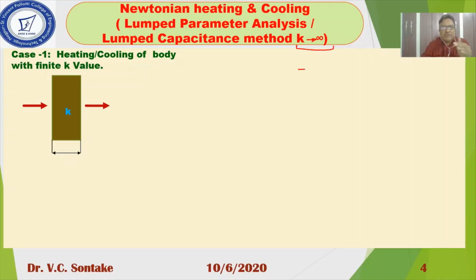It has a finite thermal conductivity value K, and its thickness is capital L. Let's say the rate of heat transfer is Q. The body is exposed to a fluid at temperature T infinity and convective heat transfer coefficient h on both sides.